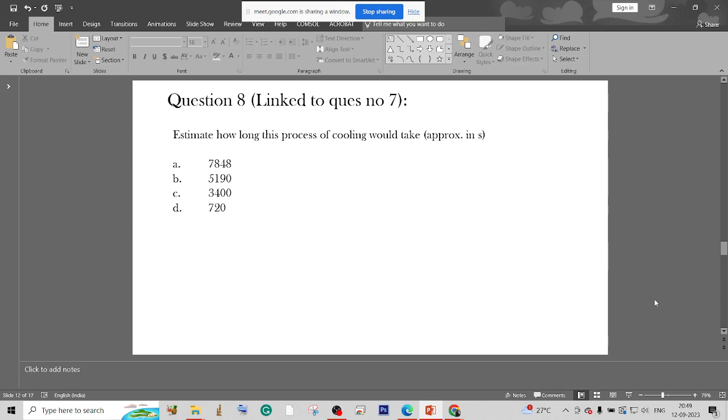How we will calculate that? The total heat transferred is how much the temperature has decreased, that is from 300 to 200. That will be the total heat, and that heat decreased within the body is equal to the heat taken away from the body to the surroundings. That will be given by Newton's law of cooling. That is one equation: the average heat is given as hA_s into (T_s average minus T infinity).